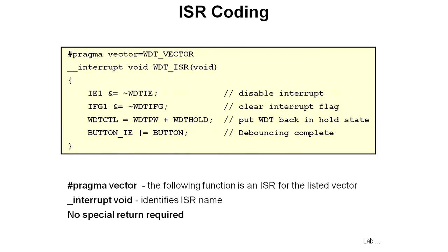So once the processor is interrupted and the interrupt mechanism has loaded the address of the interrupt service routine to be executed into the program counter, we're going to jump off and do the interrupt service routine. Here's an example of an interrupt service routine that we might write in our code. You can see we've used this thing called a pragma.